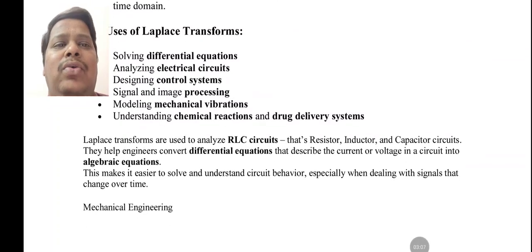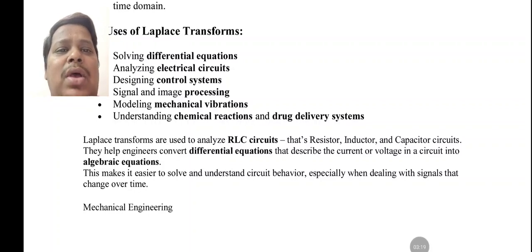Laplace transforms are used to analyze RLC circuits, that is, resistor, inductor and capacitor circuits. These help engineers convert differential equations which describe the current or voltage in circuits into algebraic equations. This makes it easier to understand the behavior of signals and changes over time.